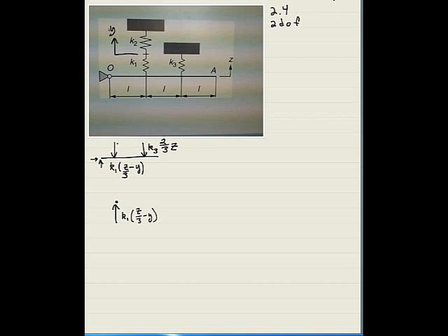The node point is also being touched by the spring K2. So to get him, I draw the line. I write an equation for it. So this is going to be K2 times the only motion that's important, which is y. And now I imagine that if y is positive, I am pushing the spring. If I'm pushing the spring, it pushes me, and so this force is down. Alright, so now that I have the two free body diagrams, what I'm going to do is